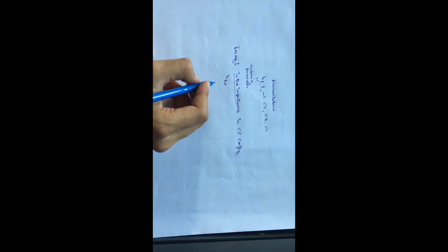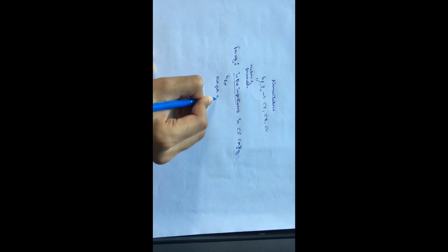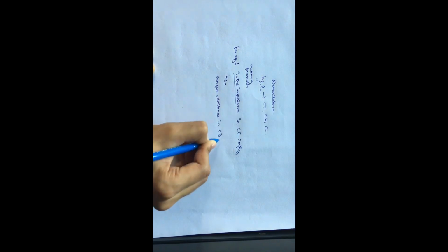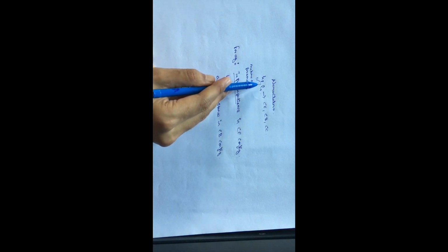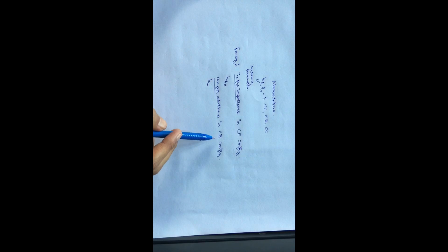For another example, if we had output admittance in common base configuration, then it would be denoted by h with subscript o because of the output admittance. We know that L1 informs us about the nature of the parameter and L2 informs us about the transistor configuration. So we have common base configuration, so L2 will be denoted as small letter b in the subscript.